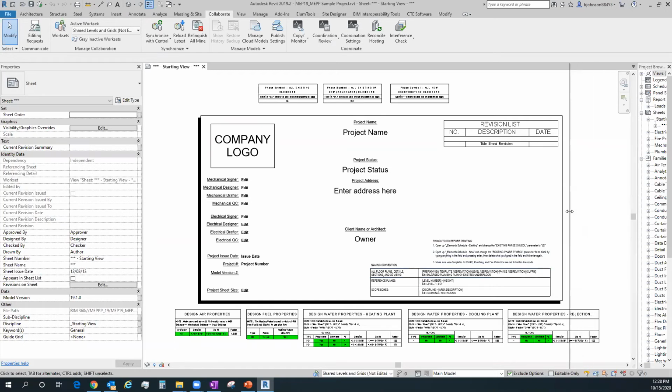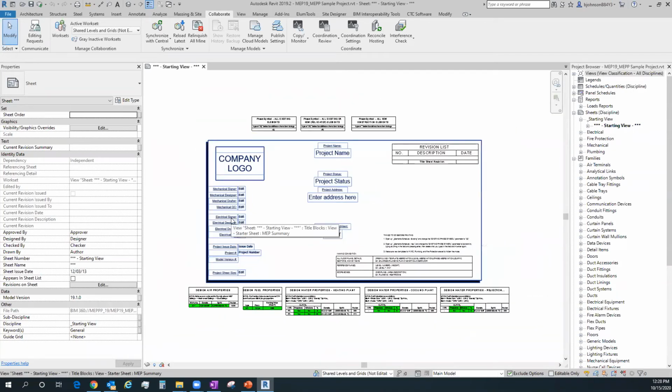That's all possible in Revit, but those room bounding lines, when you draw walls over the top of them, eventually those walls move, but the bounding lines stay there. That actually causes problems for the MEP guys because those room boundings are the boundings of the spaces as well, same as your rooms. So if you don't remove them, then they don't actually go to the wall edges, and that eventually causes some major issues and lots and lots of warnings inside of Revit. So that's just one of those areas I like to have cleaned up as soon as possible.